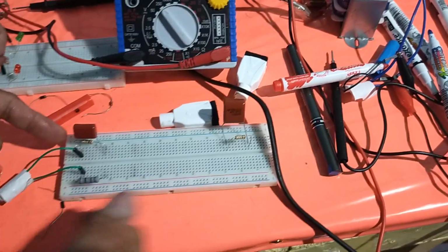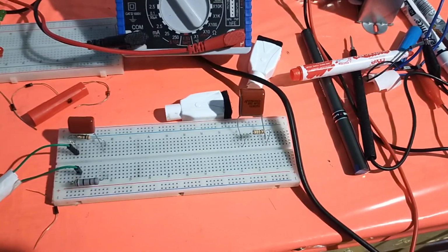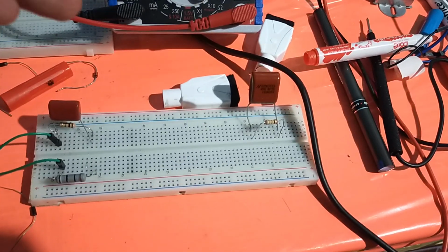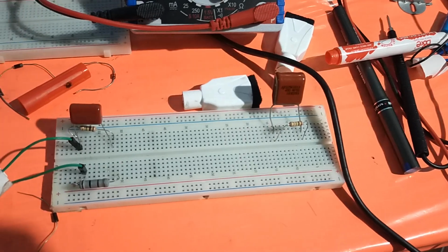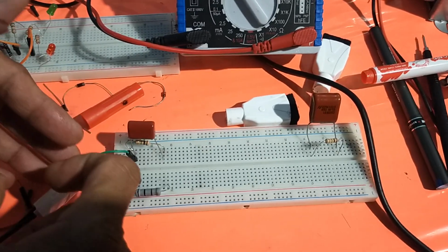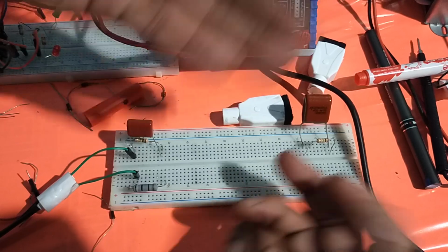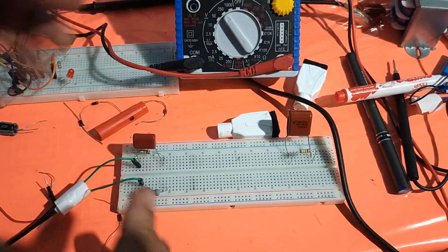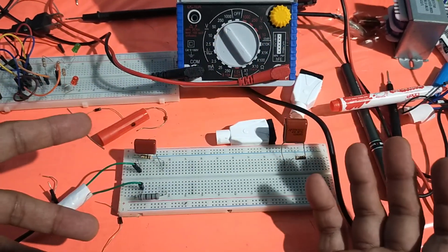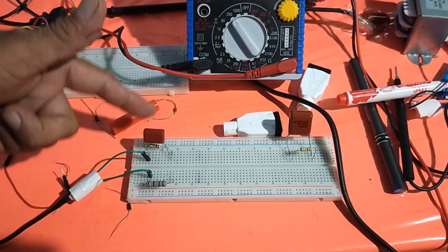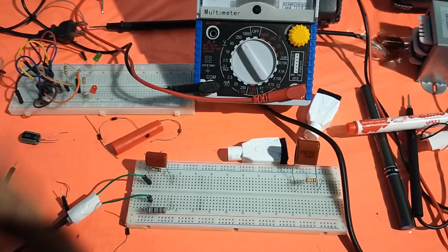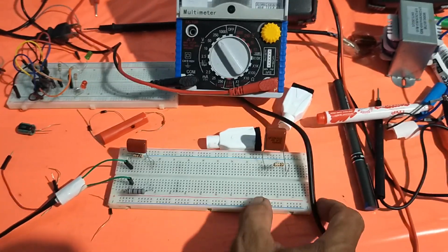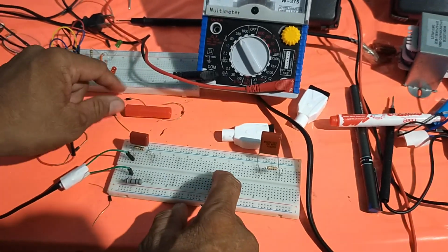We call this circuit here the step-down circuit, because this capacitor will drop a certain amount of voltage to lower down the voltage from the outlet. The 230 volts here will be lowered down to 12 volts. Actually, the voltage is lowered down capacitively by the action of this capacitor. That is why we call this power supply a capacitive power supply. Then the next stage is to